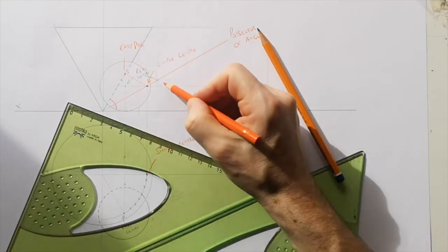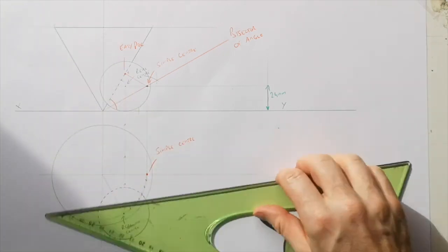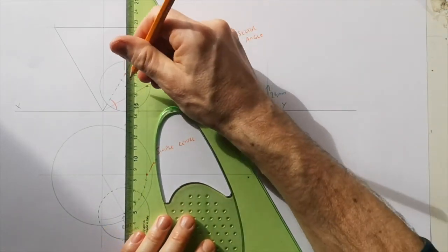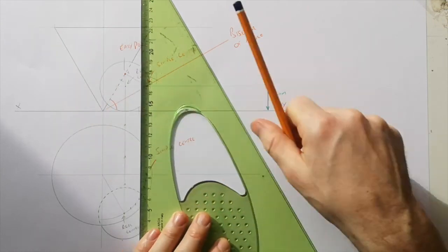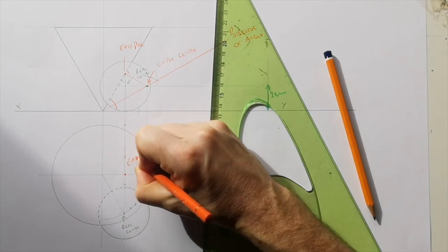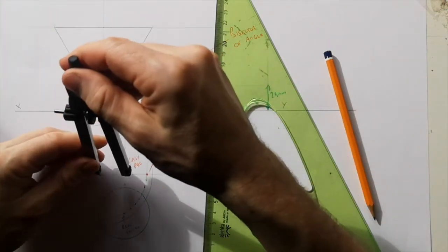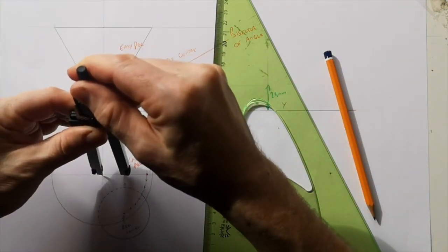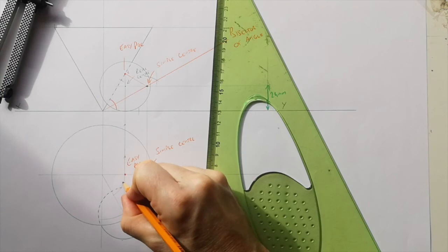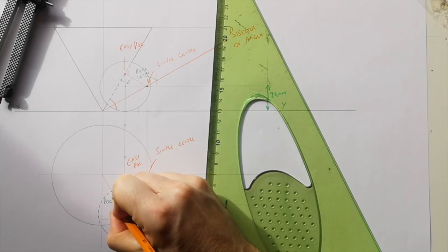Okay, it's when the whole thing was out here. Well, that easy point of contact had to be along this line. So let's go down and find it. We just project it down. That's coincidentally right above the center. That's just coincidence, to be honest. Easy POC. And like everything, that just rotated back. So we had the easy one. There it is there. It rotated back until we got to the 60-degree line. And there it is, point of contact.